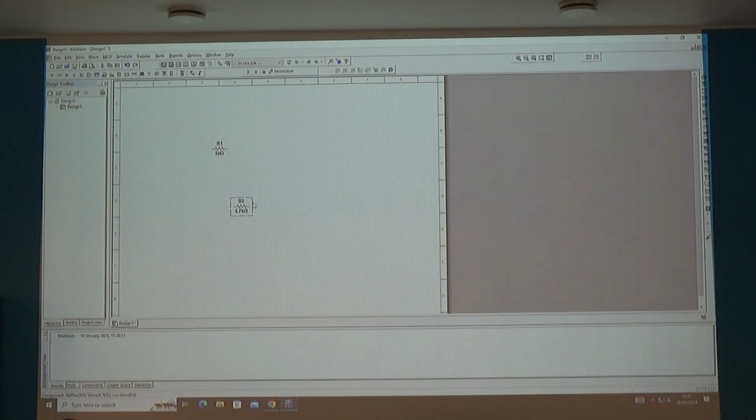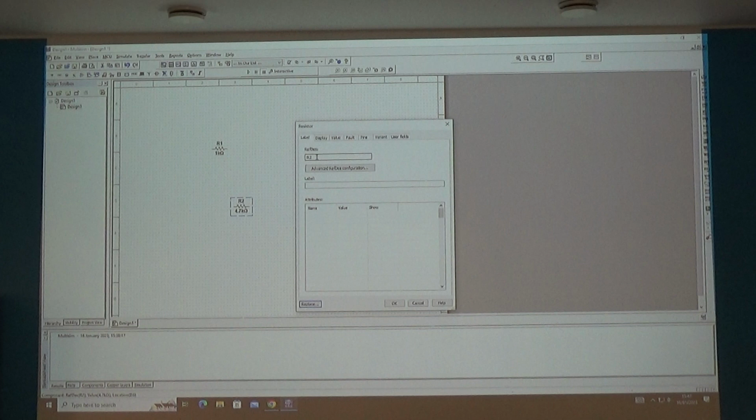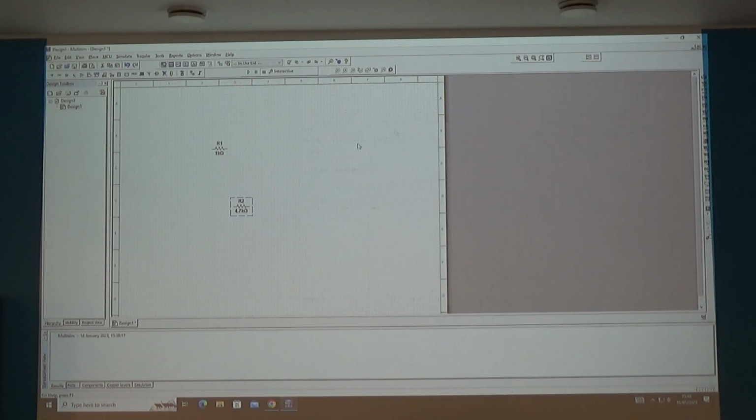Okay, so you go over the top of the component and you click with the left mouse button. Be careful that you don't click the legends, because if you do, you can change R2 to a different value if you want. Look. So you can go in here and you can change the label. I can change that to R27.5 if I wanted to. But I don't want to, I want the whole component. So I click on the whole component and I get a blue box come around the whole component. Right, that means it's highlighted. I'm now in editing mode for that component.